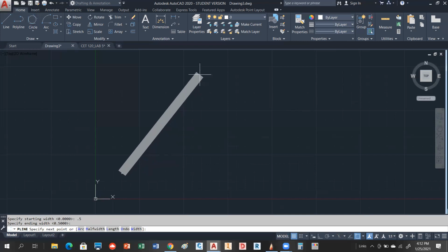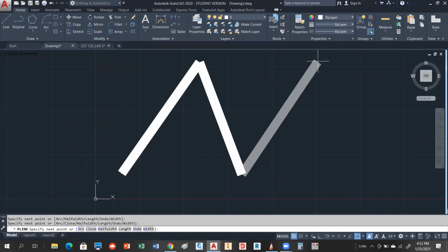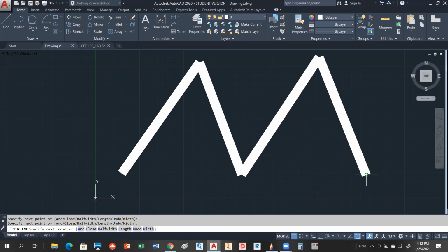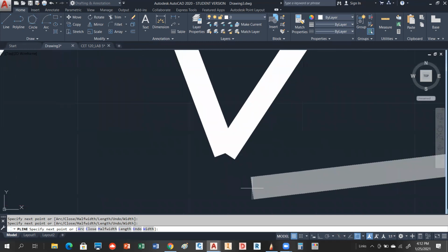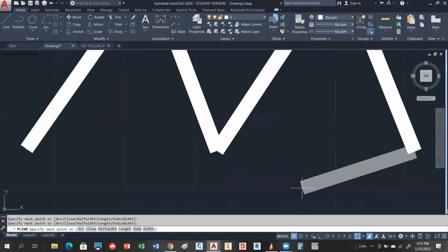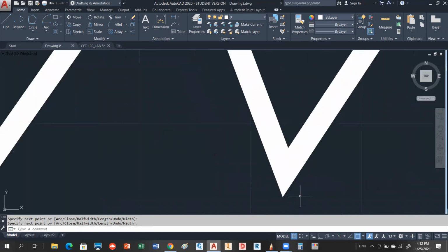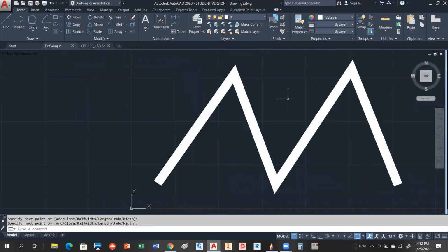And notice now as you draw, go ahead, and if you're following with me, you're putting some lines in. You notice that what you're getting is lines with width. Now you might notice too, this looks pretty nasty right there. It's not like beveled shut. But what will happen is once you put the last point in and then you hit enter, notice how it fixed itself. So it's fixed it nicely right there.